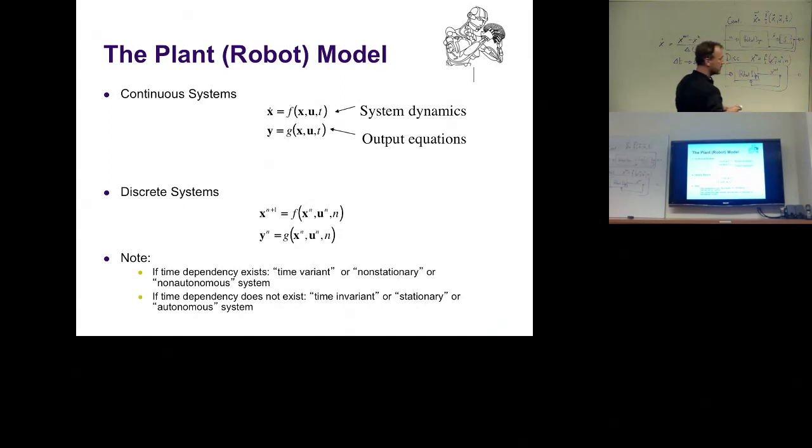And it's a good approximation. So it's very easy, from just 2 time steps, to get velocities by numerical differentiation. There are other states which are much, much harder to estimate. For instance, if you have a humanoid robot and you want to know the orientation of what is called the base coordinate system, let's call it the butt in this case, it means: where is the base coordinate system in a 3D world, and what orientation does it have?